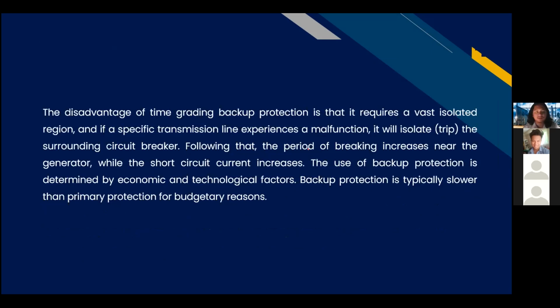Next. The disadvantage of time grading backup protection is that it requires a vast isolated region, and if a specific transmission line experiences a malfunction, it will isolate or trip the surrounding circuit breaker. Following that, the period of breaking increases near the generator, while the short circuit current increases. The use of backup protection is determined by economic and technological factors. Backup protection is typically slower than primary protection for budgetary reasons.